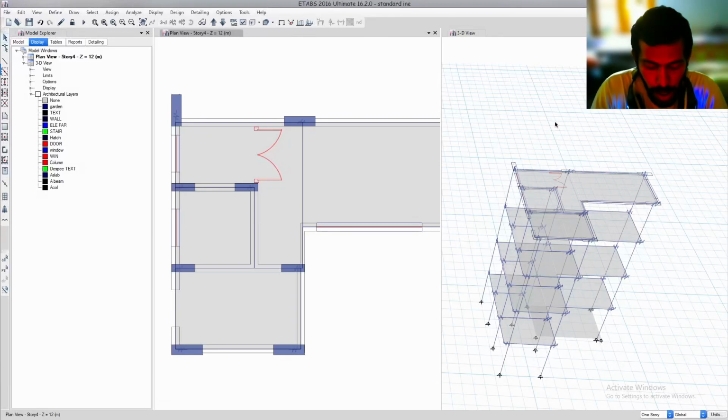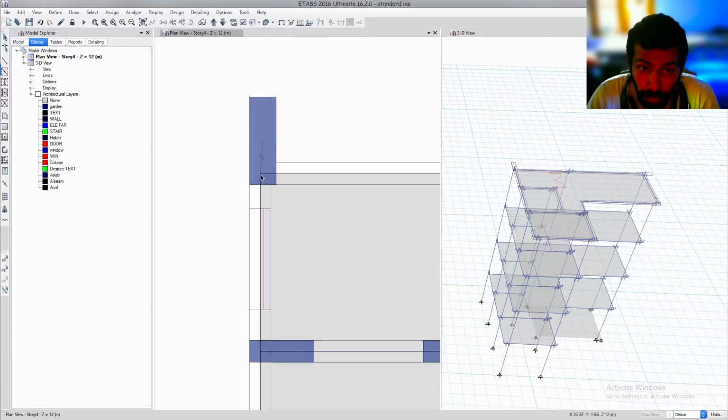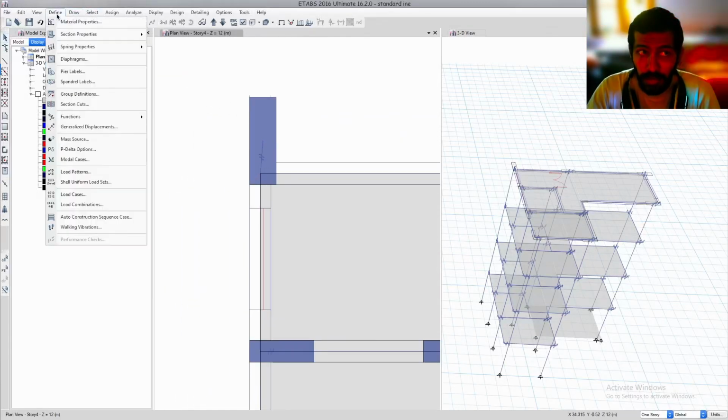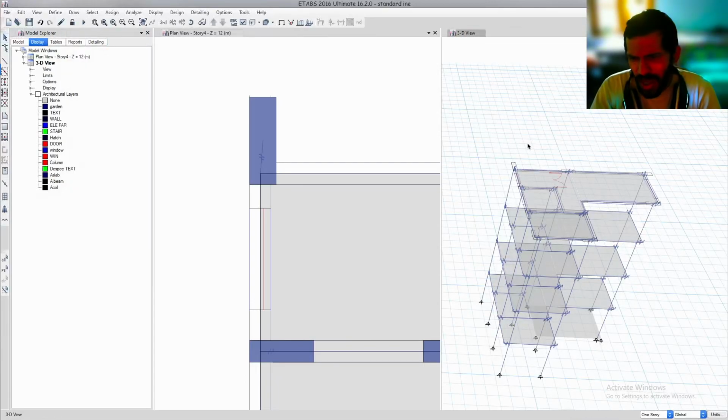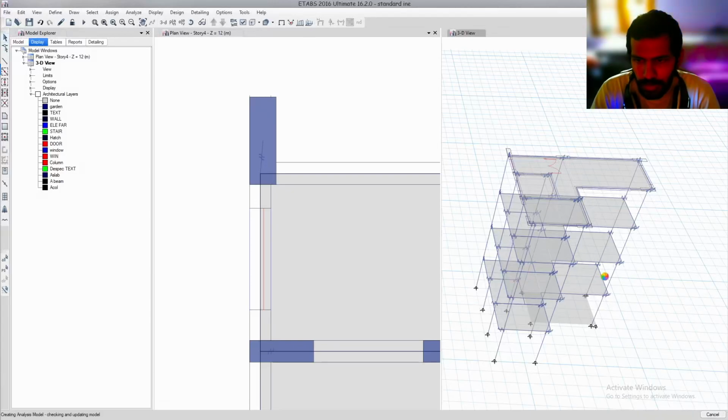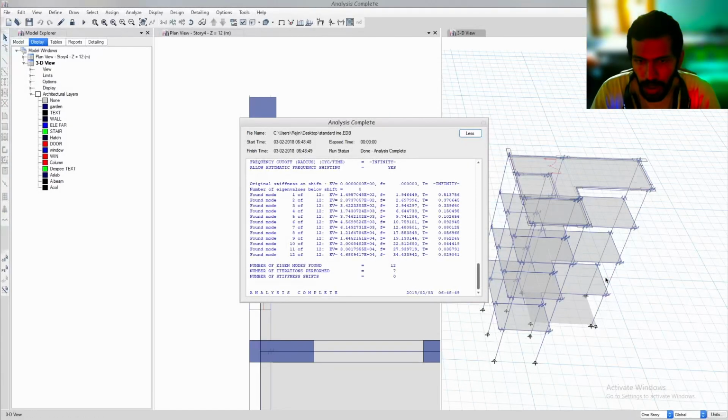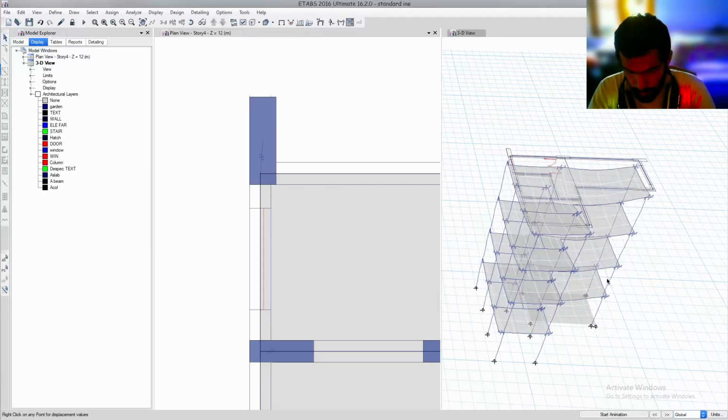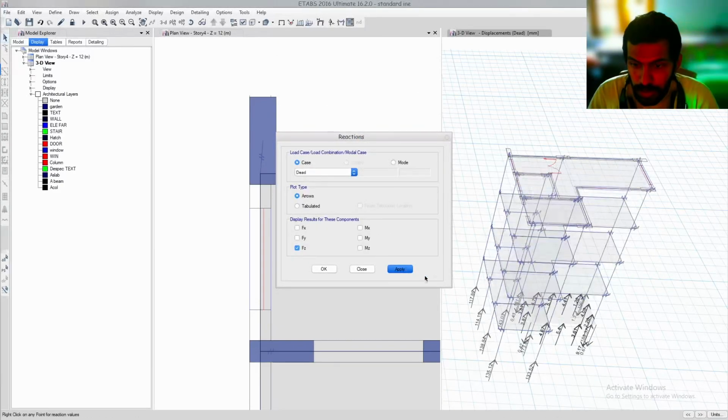Thanks for watching. This is by far the smartest method in exporting a CAD file right into ETABS. If the columns are out of order, it really doesn't matter. You can anytime define a link and draw the asset here that will transfer the load from the slab or beam to the center point of column. Then only the load will be transferred into column. Let's try to analyze it. There's only self weight here, I think. And if you go for any sort of support reaction, you can see the asset is right there.